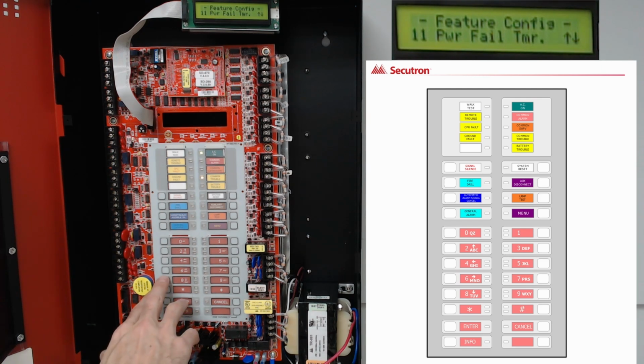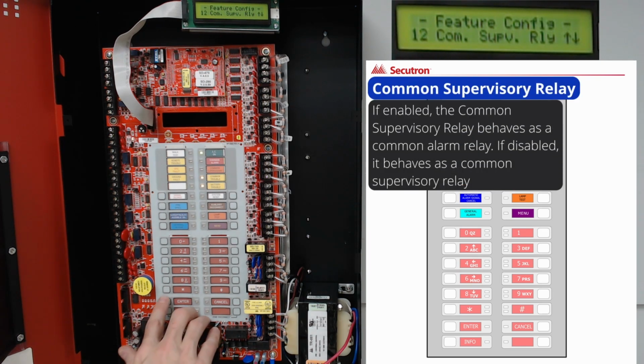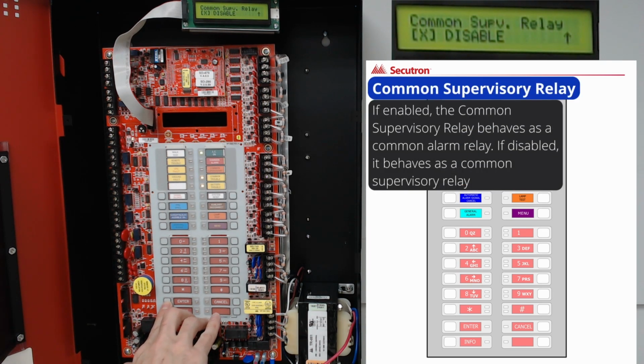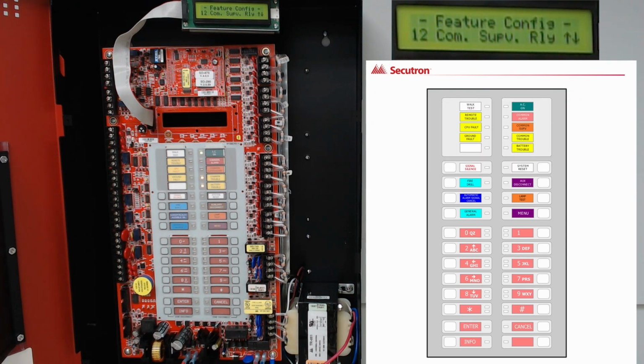The next option under Feature Config is Common Supervisory Relay. By pressing Enter, we get to see the option for Common Supervisory Relay. By default, it has been selected as disabled. By hitting the up cursor and then the left or right, we can then enable the Common Supervisory Relay. And we'll press Enter and Cancel to exit back out to the previous menu options.